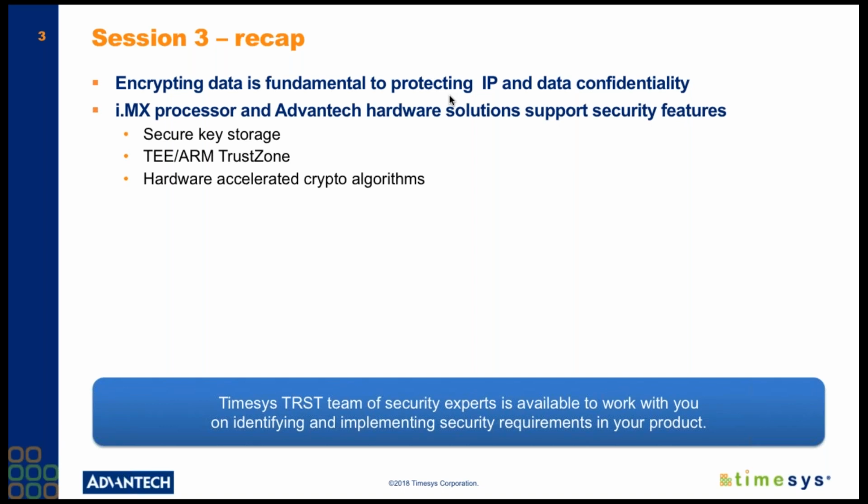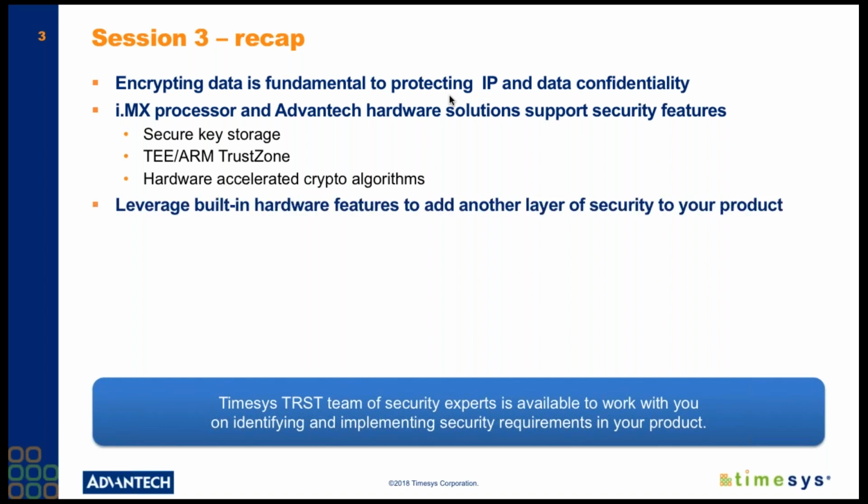With Advantech hardware that's equipped with the i.MX6 processor, there are a number of solutions that assist with protection of data. We discussed secure key storage that was used to store the keys used for encryption. Akshay was also talking about TrustZone in the ARM architecture, and we discussed use of accelerated crypto algorithms to assist with the encryption of data.